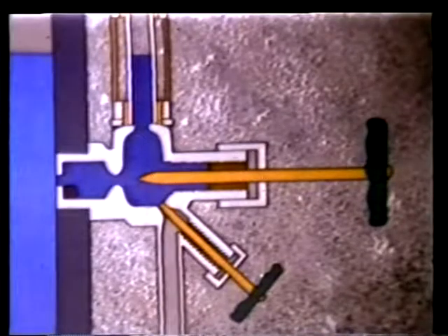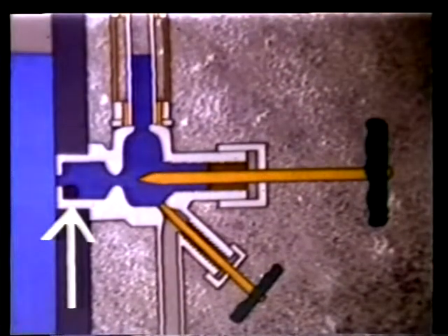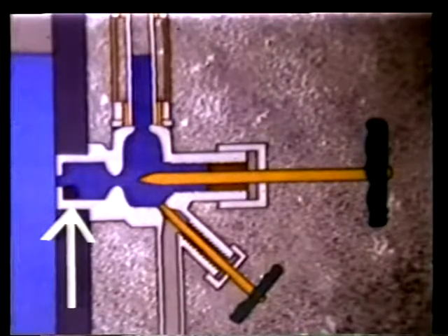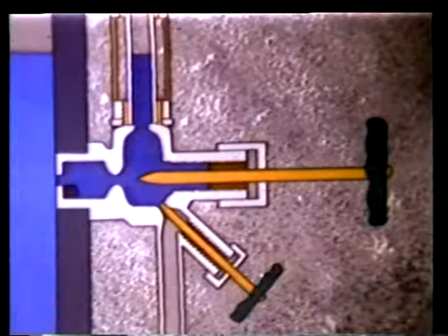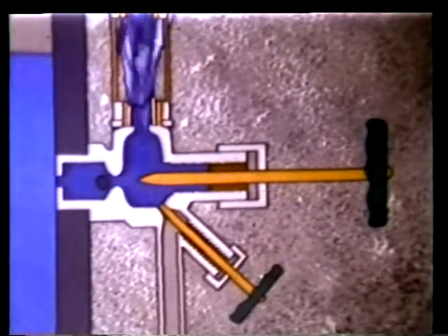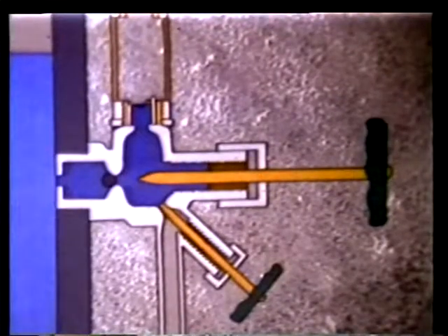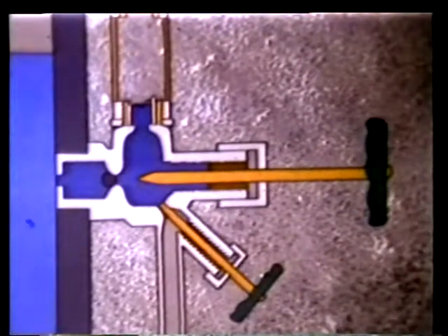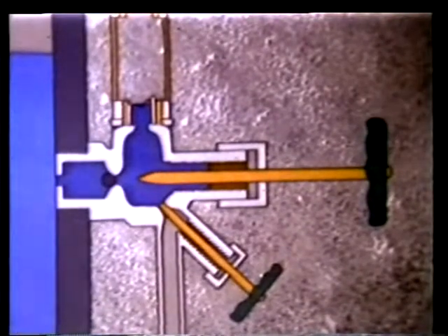One special feature is that the valves often have a ball check built into them. The ball check cuts off flow if the gauge breaks. When fluid rushes out of a broken gauge, the ball is forced into an opening inside the valve, which stops most of the flow. This keeps the gauge from leaking uncontrollably, even if the glass is broken.